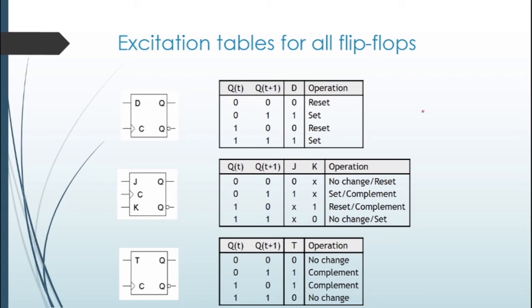Similarly, if we don't want to use two inputs for flip-flops like JK, we can simply use a D flip-flop, and D flip-flop is very simple. We don't need the last state value, we just see what the next state value is for each state element, and we generate those from the flip-flops.